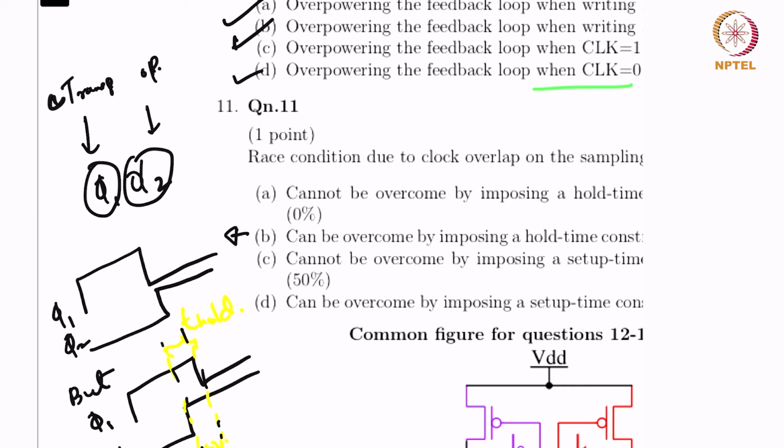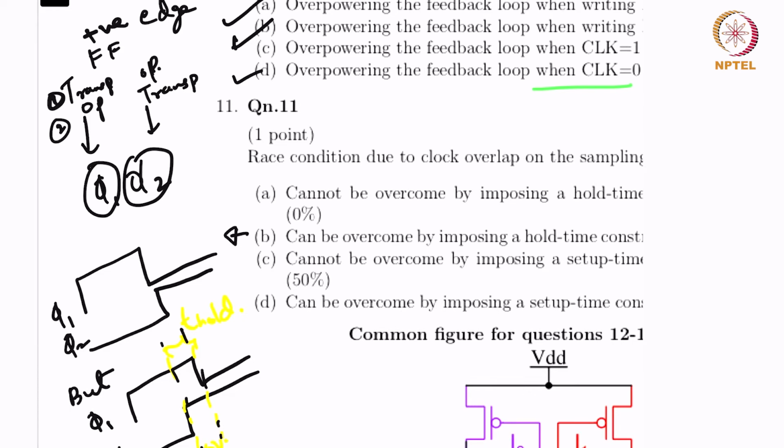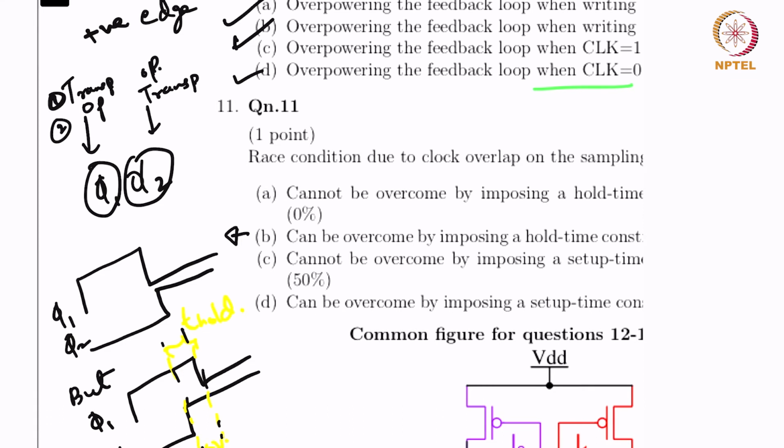So after this phase, latch one becomes opaque and latch two becomes transparent. And this is for a positive edge triggered flip flop, right? Or positive edge triggered system, wherein you have a latch here that's controlled by phi 1 and a latch here controlled by phi 2. Now when you look at it, the data, right?